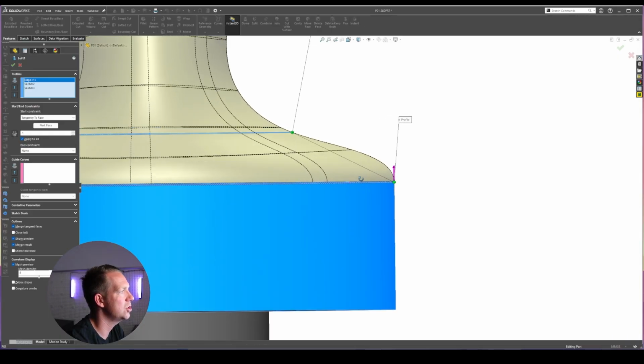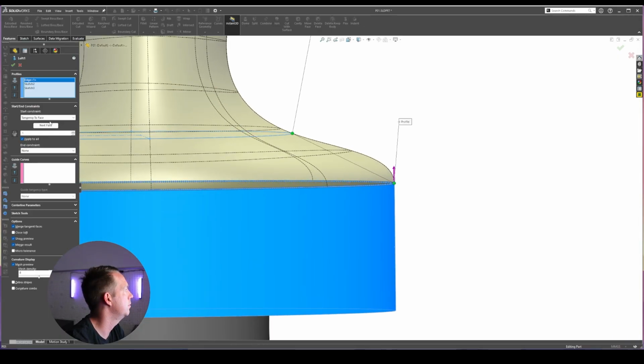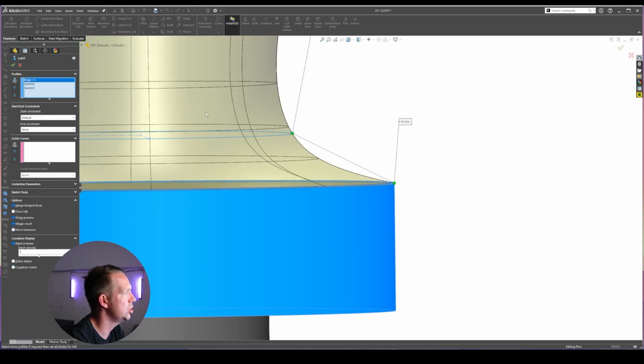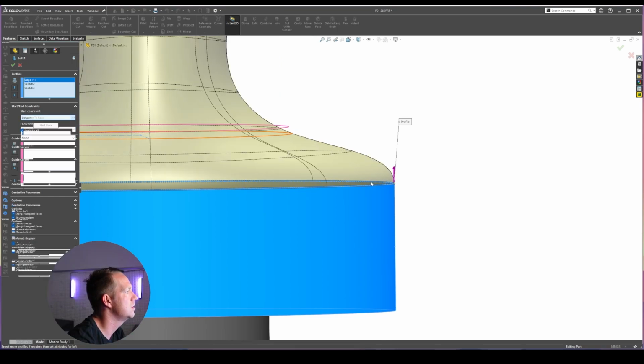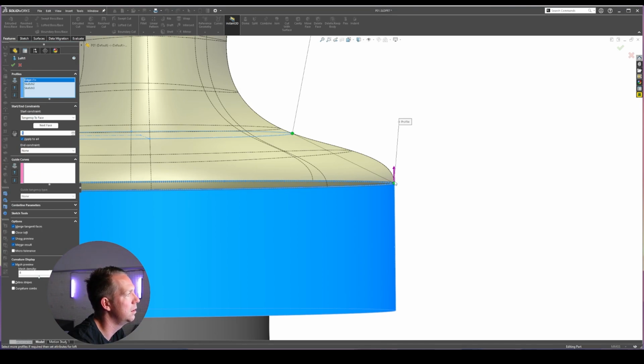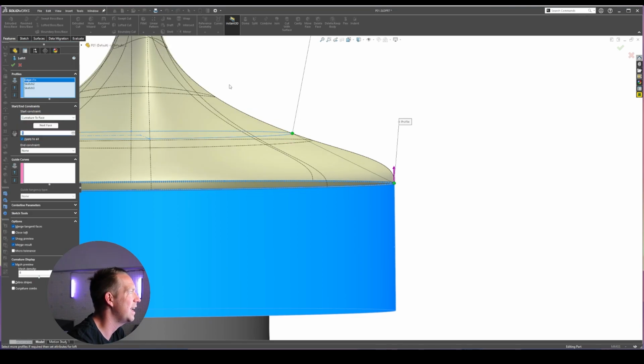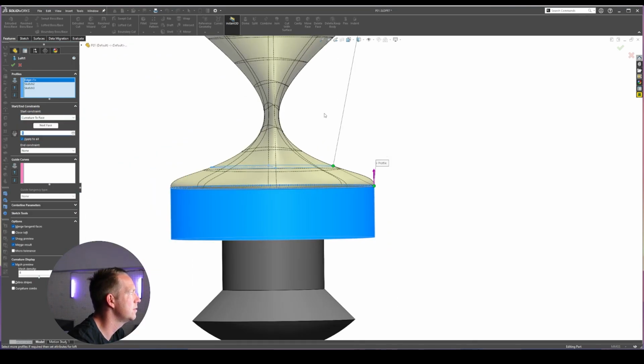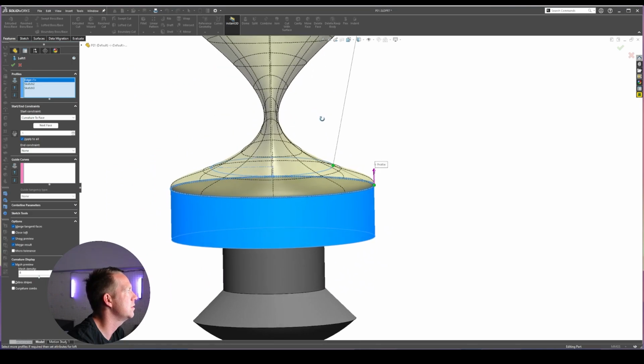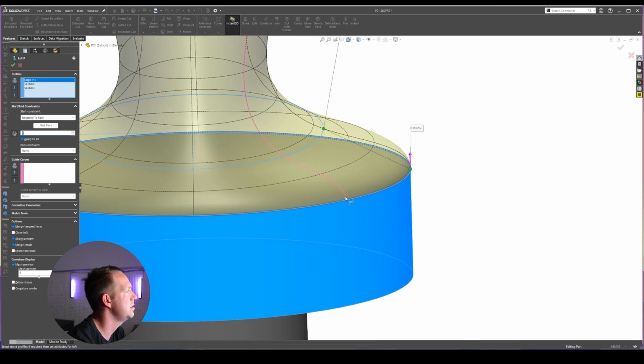And so you can see how the shape has changed from being a very sharp join, where it's just purely guided by the profiles that we've selected, to, in this case, something that has a nice curve to it to be tangent to that face. Now, if I change that to curvature to face, you can see that it's, again, a very slight difference, but a dramatic difference to the shape of the loft. Let's go back to tangency to face.